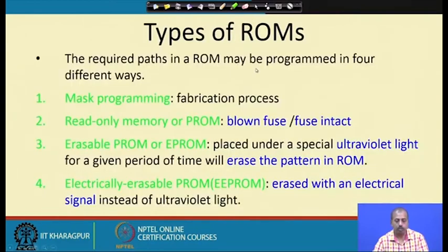Next, we will be looking into other types of ROMs. There are different types of ROMs. The very simplistic type is known as masked ROM, which is fixed at fabrication time itself. Then there is programmable read only memory, or PROM. Normally we have a programmer available, which is hardware circuitry. You can put the ROM in a slot and apply some high voltage, and accordingly the ROM will get programmed. The different locations of the ROM get different values.